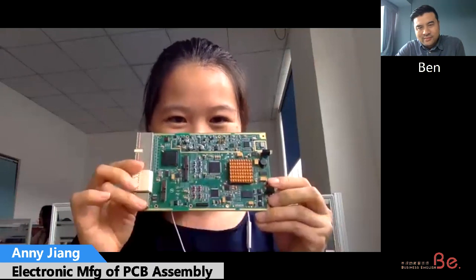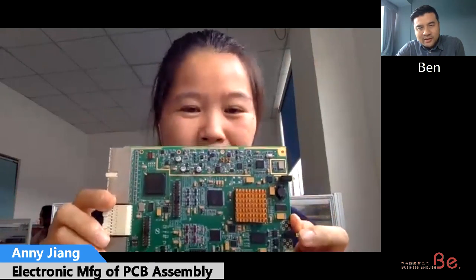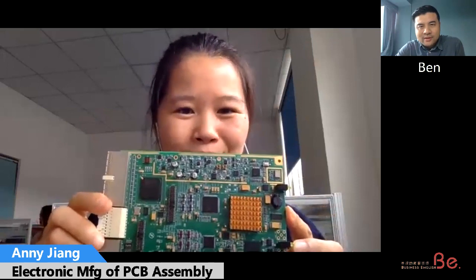Got it. So what do you do? Tell me what you do. We are in the electronic manufacturing business. It's kind of EMS, like Foxconn. Okay. So you make PCBA. You buy the PCB, you do the soldering, am I right? Yes. We buy the PCB and the components, and then SMT onto the board, and then programming and functional testing, case assembling, cable assembling, and then final shipment. Okay. So it's quite a typical process.